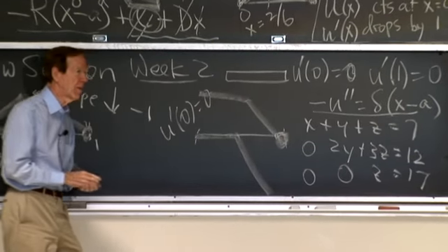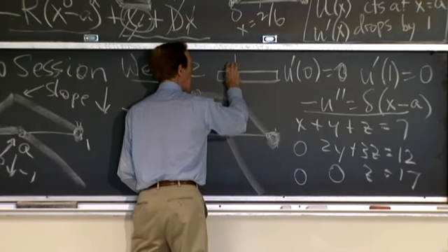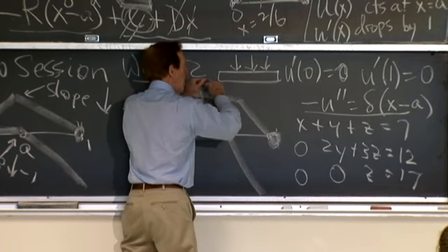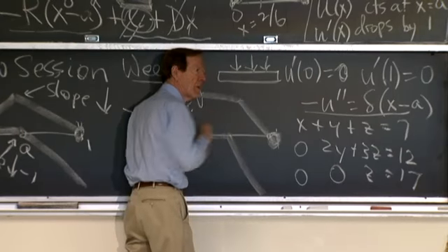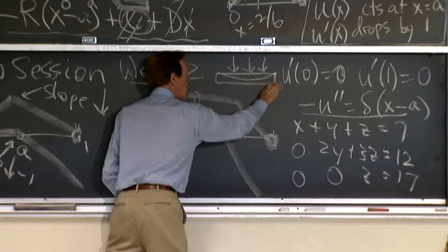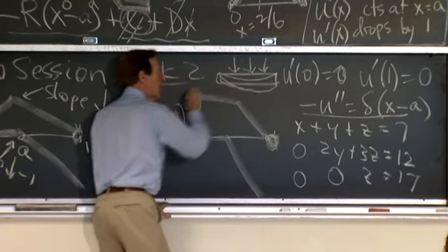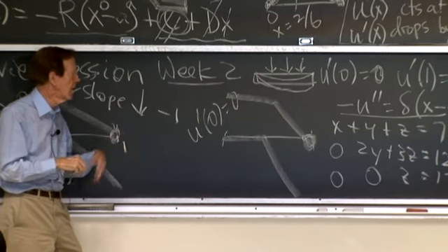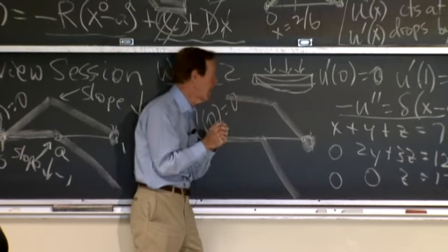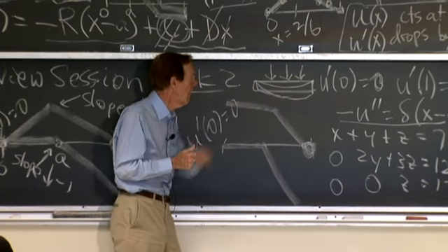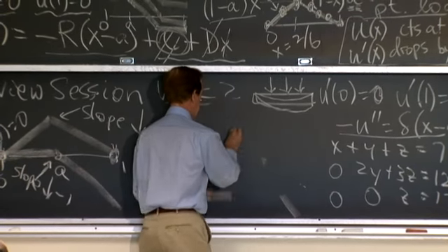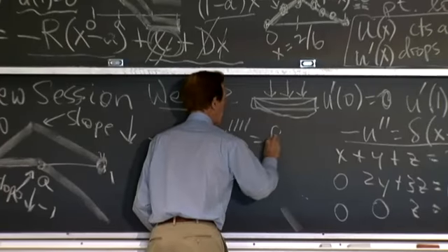I like the beam better this way, because the point of the beam problem is loads are acting, and we'll see this, of course, later. Loads are acting perpendicular to the direction of the beam. That's why the beam bends, so it'll bend a little. And that is what leads us to its bending moments and other stuff. If you haven't met beams, it'll be great to have a lecture about beams. That gives a fourth order equation that I'll write down again. Fourth derivative equals the load.